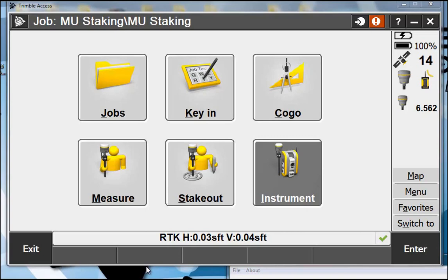So the first thing I want to start with is the DXF file. So we're just assuming he's exported all these files. I have them all loaded now in my data collector. Just have to put it in the location on our Trimble data collector wherever our job file is stored. So I have a specific project folder for this job. These files need to be in that project folder. If they're somewhere else, it's not just as easy as loading it up. I got to go hunt and find it. So file management here for working with these external files is key.